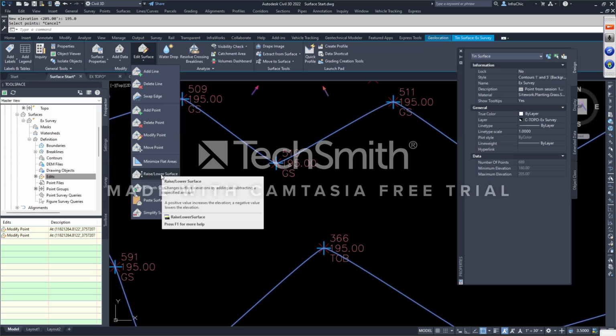It takes it and lifts it from where it's at today, whatever datum adjustment you need, up 0.3, down 0.2, whatever. Why would I raise a surface? This comes into play with GIS, which is why I have this GIS file in the background. Because GIS's datum is, most of the time, not the same as the datum I was given by my surveyor. A lot of the time, the surveyors go out there and they survey it to their heart's content. They set a base point or they set a control point and say, that's it. And the control point's this elevation.